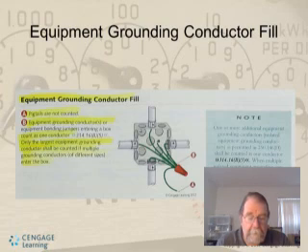If it has one or more additional equipment grounding conductors, which are your isolated equipment grounding conductors, as permitted in section 250.146(D), they shall be counted as one conductor. Under 314.16(B)(5), when multiple isolated equipment grounding conductors of different sizes enter the box, only the largest is counted. So essentially what that means is only one conductor will be counted. The pigtail isn't counted, and the other three conductors are not counted if they're 14 gauge, and then if you got the 12 gauge coming in, that 12 gauge would be counted as one conductor.